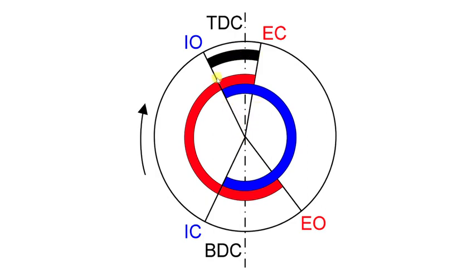The piston comes up, it's approaching top dead center, we're having our explosion, and then it's going to start coming back down again. With that in mind, this actually looks quite early. Normally I'd expect it to be about here, maybe 5 or 10 degrees before top dead center. It looks a lot more on this diagram. But anyway, the point is, we start injecting fuel, we compress it, it ignites, we get our explosion.